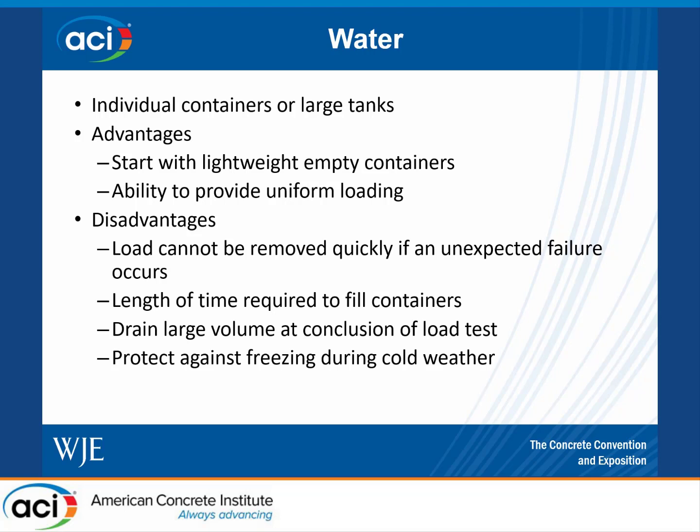So we'll have the contractor test this, a week out, and tell us how many gallons per minute they can supply, so we know how long it's going to take to fill up an area. You also have to drain a large volume at the conclusion of the test in a very controlled manner, and that's important to plan out ahead of time. And one thing that you might not think about is just protecting against freezing during cold weather. Sometimes we're forced to perform these tests during cold weather months due to various requirements, and freezing of the water is a concern to deal with.